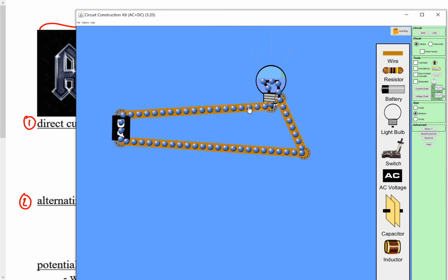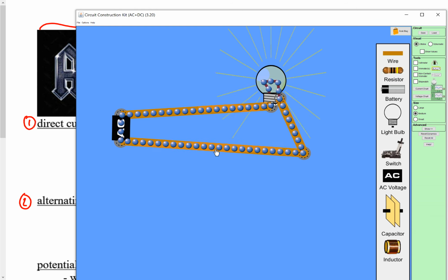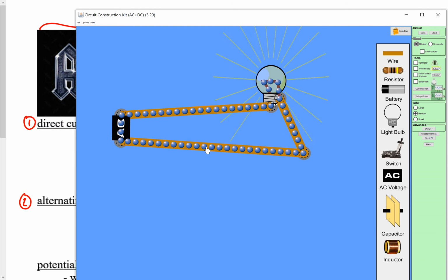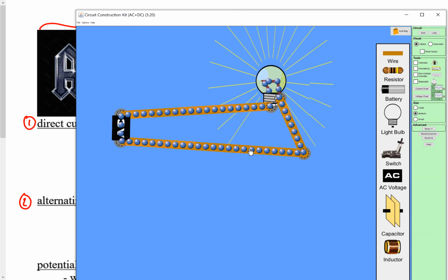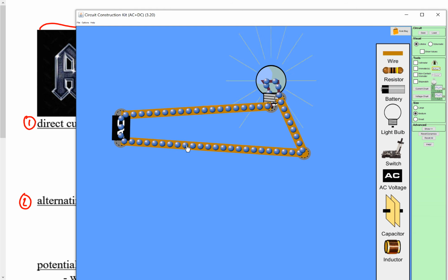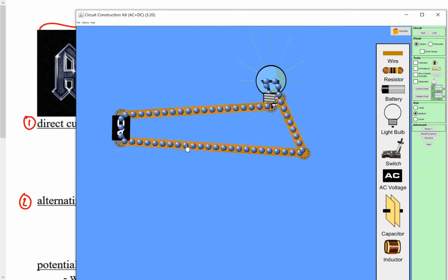There's something known in physics as drift velocity, which is basically how fast the electron is moving in the wire. I once asked a question about a shed behind somebody's house. It was a trick question, because I asked how long it would take, in seconds, for the electron to reach the light behind their house. With AC electricity, like this electron here that I've got my finger on, that electron is never going to reach the light, because in AC electricity all they do is oscillate.